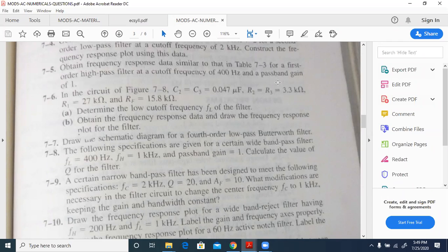So for the high pass filter, for very high frequencies, the passband gain will be equal to 1, and for low frequencies it will be 0. For the cutoff frequency, it will be 0.707 of the maximum value. Maximum value here is 1. In other cases it might be a little different. So I think that makes sense.